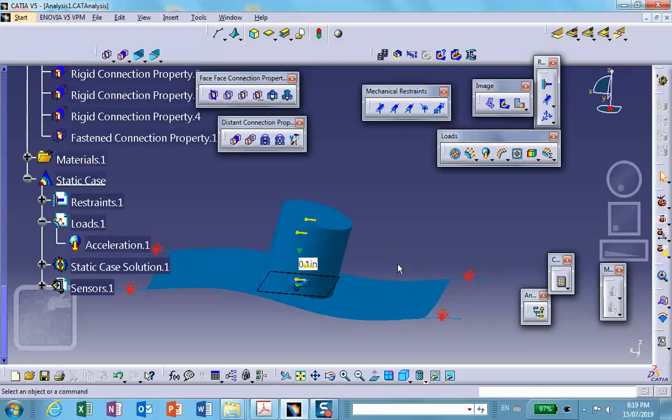Okay, the reason this is happening is that we are not really solving for acceleration, we're using D'Alembert's principle, where the force acting on the object is actually in the opposite direction. Okay, negative mg. You're solving the problem as a static problem. If you are solving a problem as static, the maximum acceleration should be considered as negative mg. The acceleration should be in that direction.